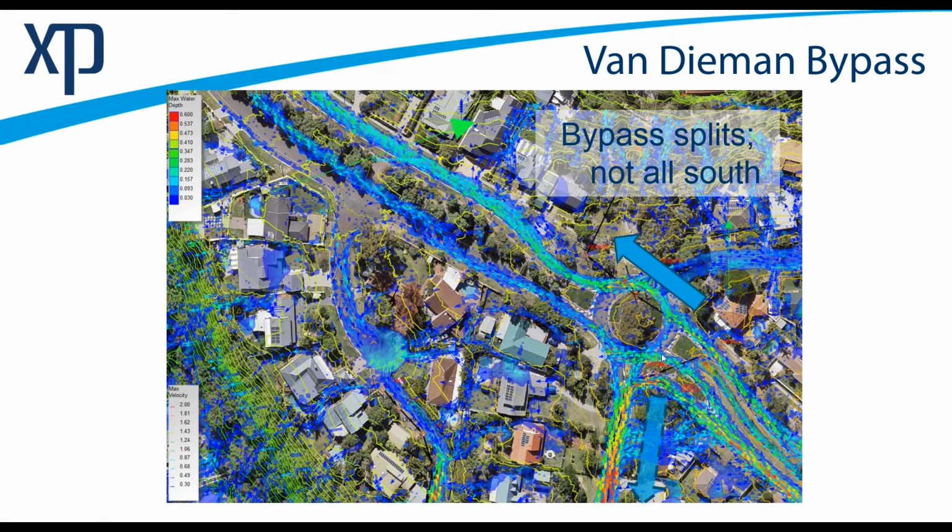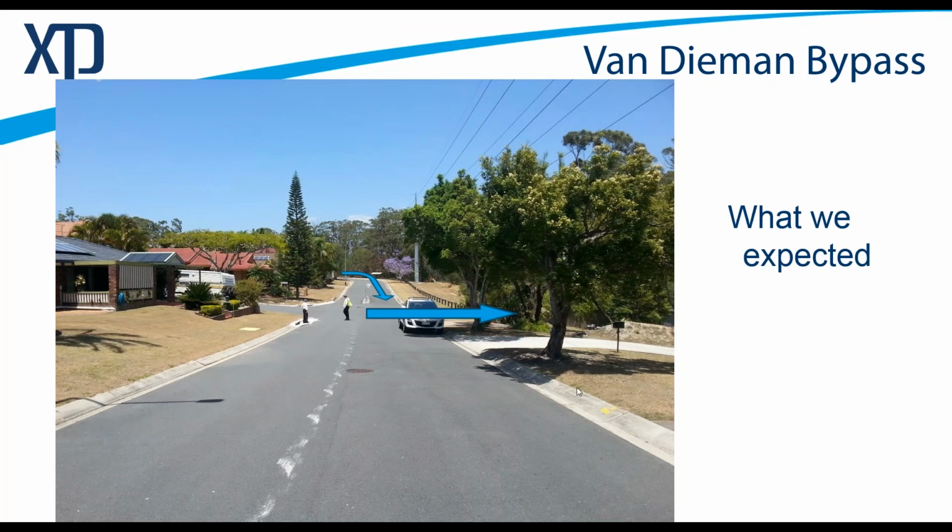One last point I'll make when looking at this is that you can see how speckly the water surface is. That's because there's no detailed survey. I highly recommend detailed survey of at least the curb, center line, maybe some of the verge, just to get laminar flow along the road. Very important here.